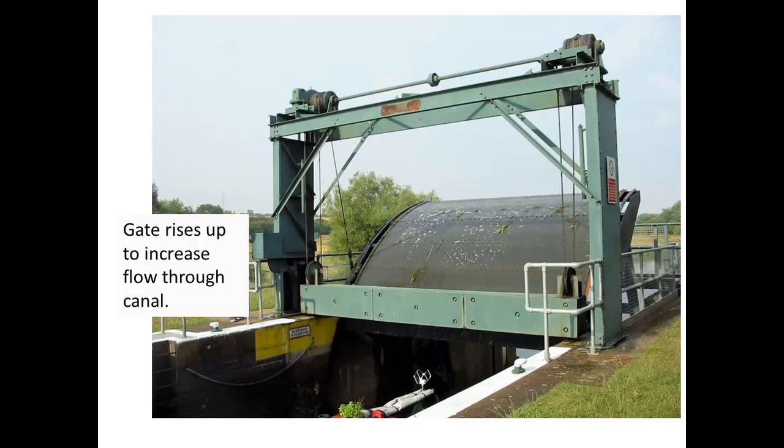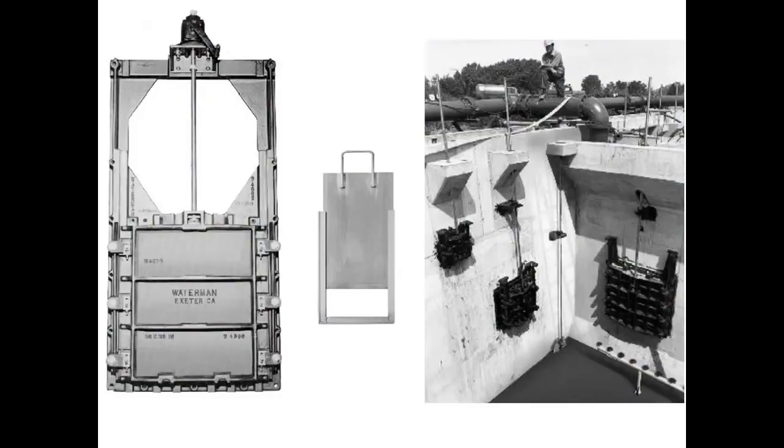Rather than having a flat surface, this gate has a curved surface, you can see. And it actually pivots about a radius, and the purpose for that is that it makes it easier to lift and lower the gate because the hydrostatic forces push through the center of rotation. In flat gates, the water is going to be pressing the gate up against the frame and increasing the difficulty of opening it.